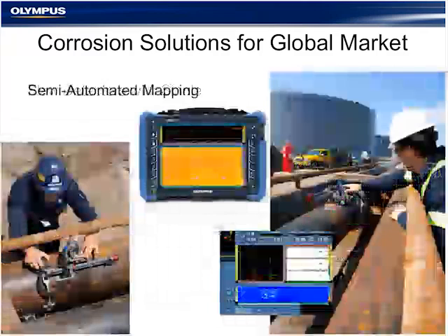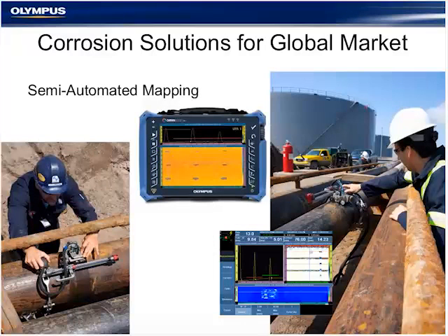Moving from there, you can get into more sophisticated solutions where you can provide much more thorough mapping of an area. So this is an example of a semi-automated mapping system, oftentimes now using phased array instead of a conventional dual element transducer. And we're using some sort of scanner to hold that phased array probe. So we have a chain scanner in this photo here in this application example. In this chain scanner, just like in the B-scan example where it's recording position information along the length of the pipe, the chain scanner is now a 2-axis encoding device. So it's reporting back to the instrument and correlating the thickness data along 2 axes.